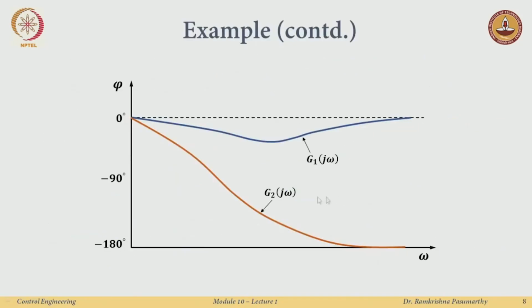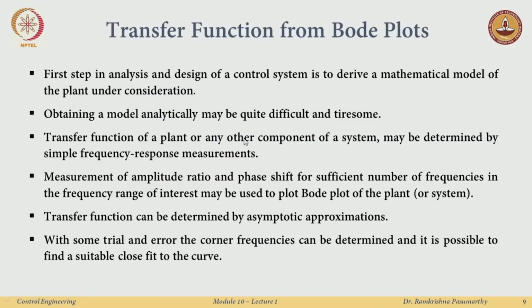Okay, so, the range in the phase angles, here it goes 0, say minus 45, and here it keeps on going down. So, this is the minimum phase system and this is the non-minimum phase system because of the range also of the phase angles. So, if I do not know the number of q's and p's, I can make use of the other definition.